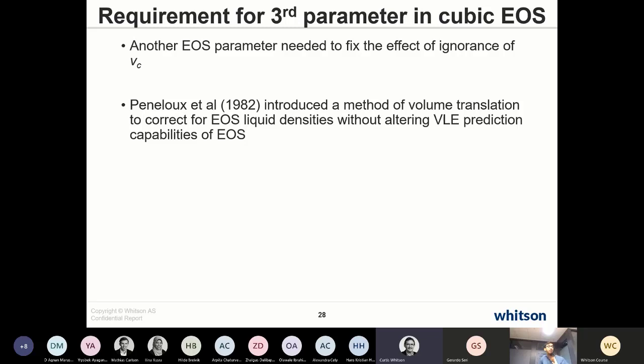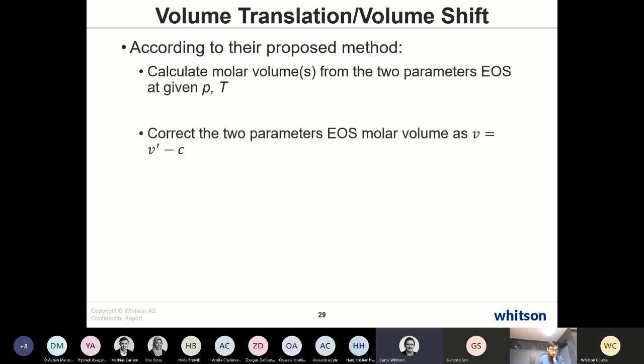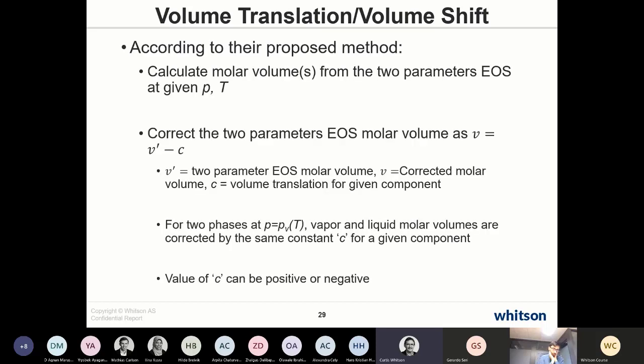So before this Péneloux, the accuracy was for SRK 10 to 40% in error, basically densities that were too low. And Peng-Robinson was maybe better, 5 to 25%, again under-predicting the oil densities. And this was just really unacceptable. So a lot of people were working on trying to fix the 2-parameter equation of state, myself included. But Péneloux and his co-authors came up with the solution being used today, very successfully, and it was a very, very clever idea.